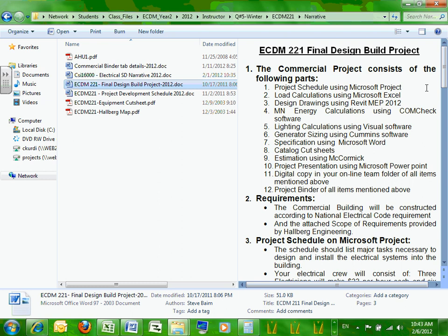We don't want to do the 18 inches by code. We're going to go 24 standard. To the top of the conduit, 24 inches of dirt above the conduits as we move them and bring them to the building.